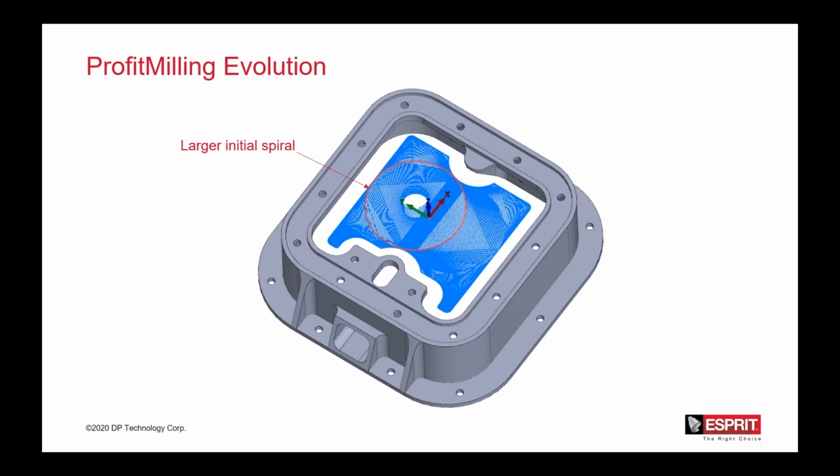Here we have the large initial spiral. So what initially happens is the tool will do a helical move down to full depth of cut. You want to always try to get almost the entire flute length. And once it's down at that full depth of cut, it's going to start doing large radial movements or spiral movements. What this does is it allows for much better chip evacuation. It'll open up that initial pocket, and you get much better chip evacuation, and coolant can get into that pocket. Instead of just jumping right into the small trochoidal movements, it'll do this large initial spiral.